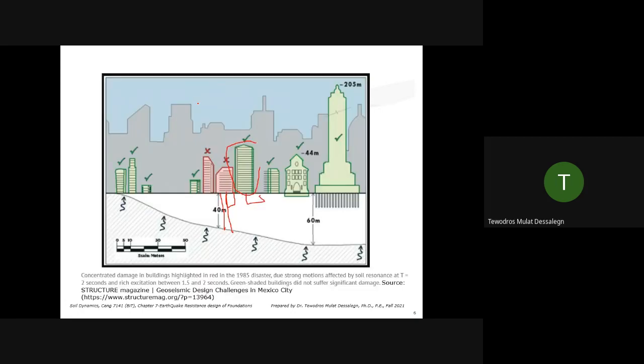So even by just doing a geotechnical investigation, by doing boreholes, by doing seismic wave propagation tests, by understanding what's underneath, where the bedrock layer is, if it is inclined, you do those wave propagations both ways, and understand the Vs of the soil layer, the Vs of the rock, everything, you can make a judgment on what kind of building to build at that site before anything starts, just at the project initiation phase. So this is the job of the geotechnical engineer. You can save lives and a lot of money by just doing this simple thing.